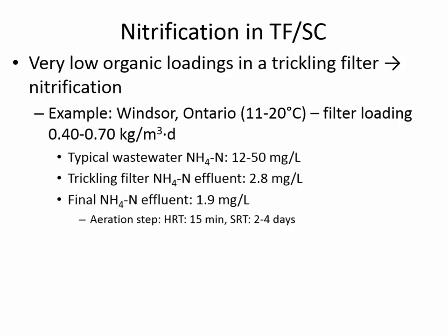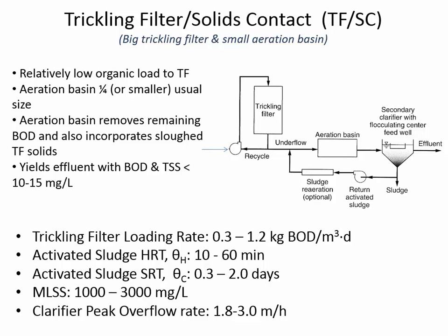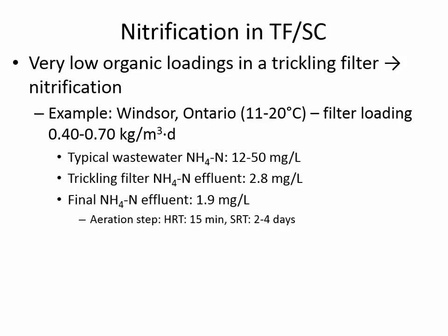You can have nitrification there because, like I said, the main event is the trickling filter, and so most of the BOD removal happens in the trickling filter, and so the aeration basin is where you would have a lower concentration of BOD, and the bacteria that can convert ammonia to nitrate are going to do that in the aeration basin. But the